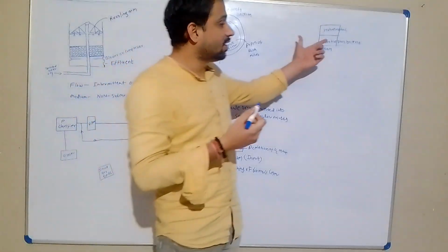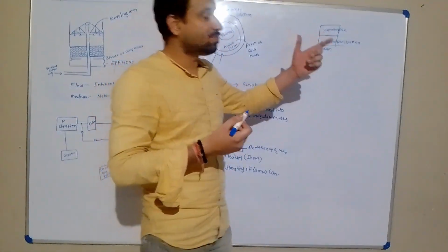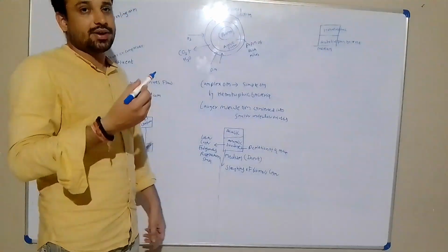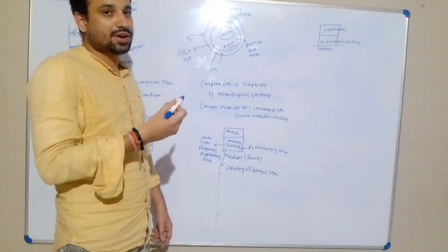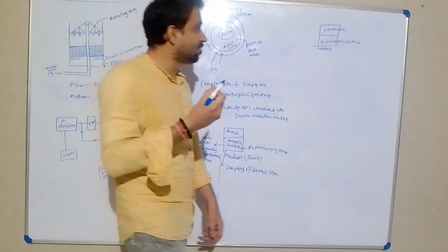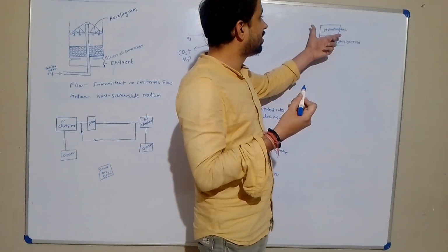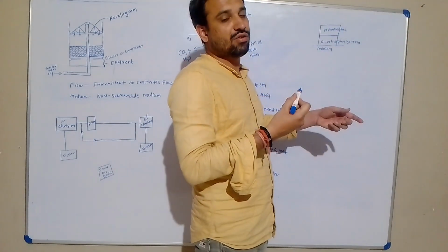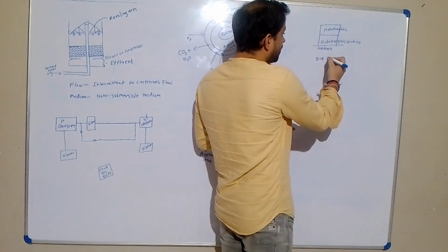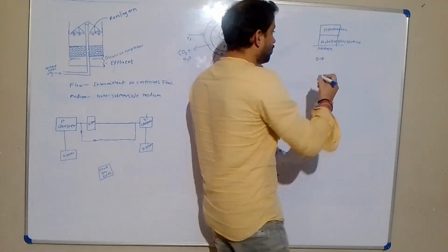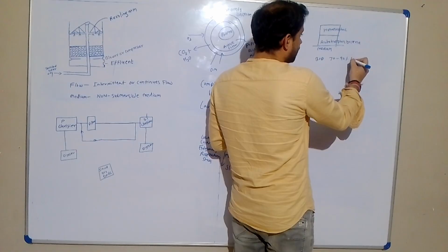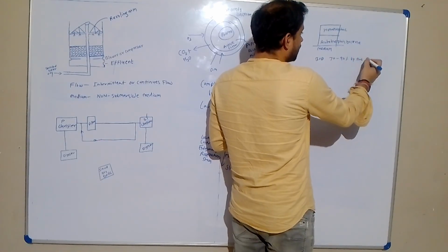It is very important. The heterotrophic bacteria are very responsible for the treatment in a trickling filter. In the trickling filter unit, the very important character is the heterotrophic bacteria, because they degrade the organic matter and the biological oxygen demand is satisfied 70 to 90% by these bacteria.